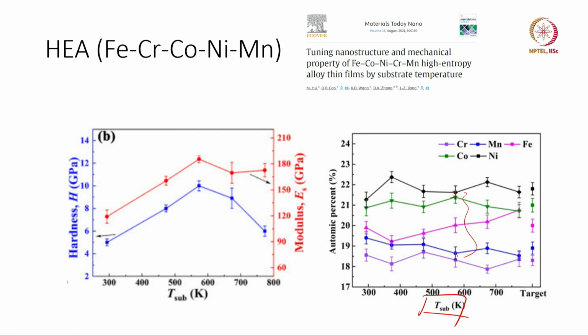Now, if there are 5 different elements, there will always be regions of microstrains, right. So, microstrains are going to be different, the fluctuations in microstrains are large. This is one of the ways of creating large fluctuations in microstrains. Very intuitively that makes sense, and because I am creating large fluctuations in microstrain, I measure a Young's modulus, right.